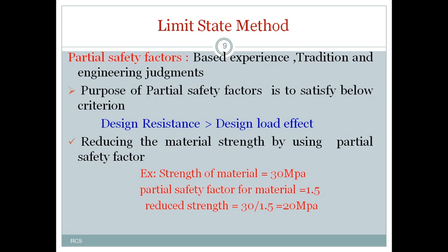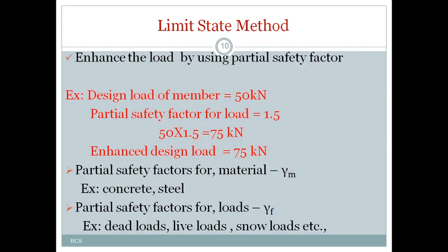If in future the load varies or increases, the material still has the capability of resisting that increased load. That's why we reduce the actual strength of the material, or the actual strength of the member, while designing that particular member. And similarly, this factor of safety is also used to enhance the load. Why should we enhance the load? I will explain that also with the help of an example.